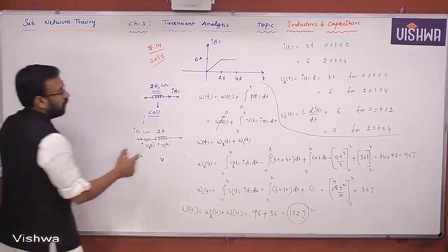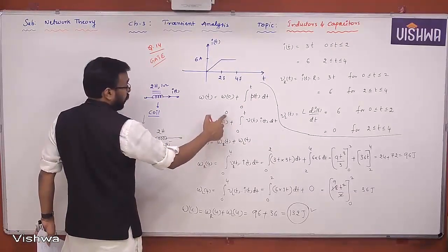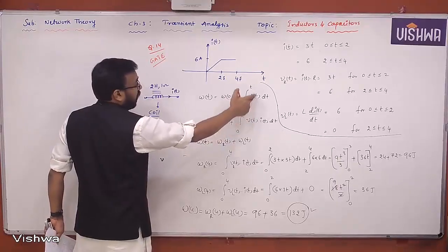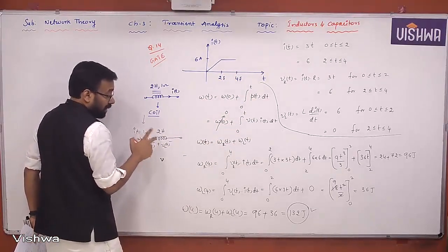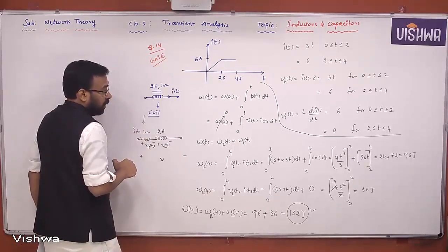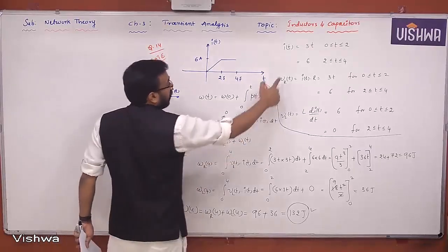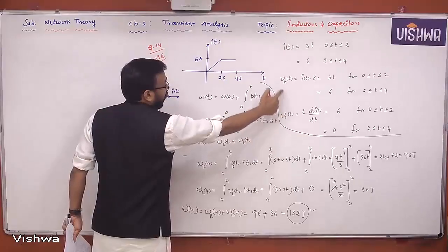It's simple, that energy power relationship, that's it. Initial energy is assumed to be 0. For energy, you require power, instantaneous power. For that, you require instantaneous voltage and current for each element, because there is an inductor as well as a resistor. Both the elements are there, and both of their characteristics are different. That is why if you know instantaneous current, because they are in series, you can find voltage of each element.